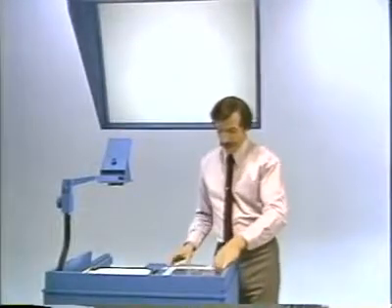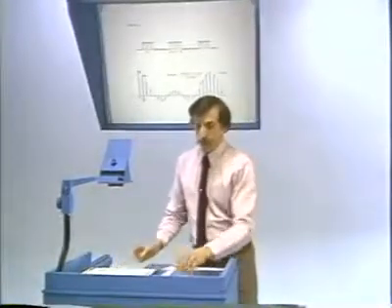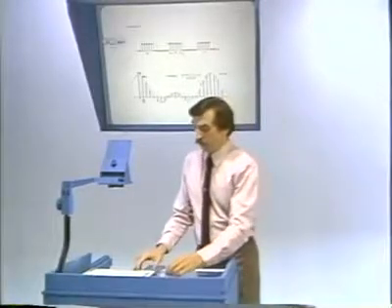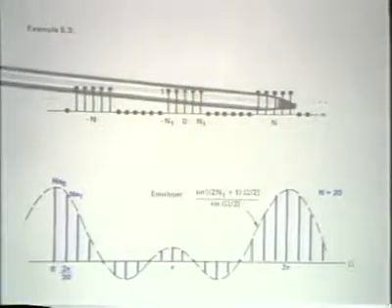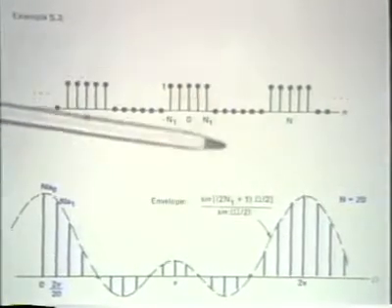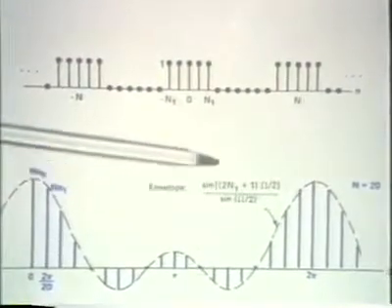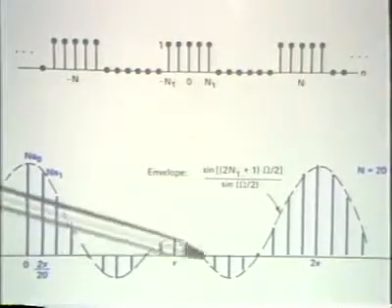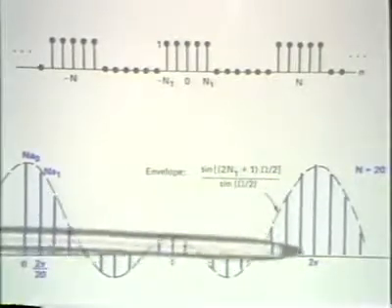And of course, we saw this in the context of our square wave example. In the square wave example, we have a periodic signal, which is a periodic square wave, and the Fourier transform of one period represents the envelope, and here we have the envelope function, of the Fourier series coefficients, and the Fourier series coefficients are samples.